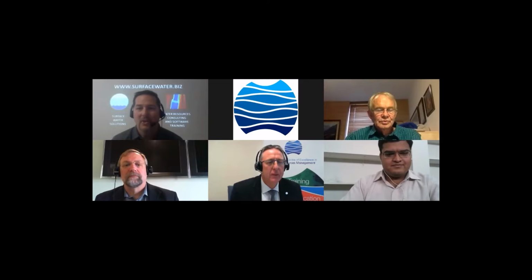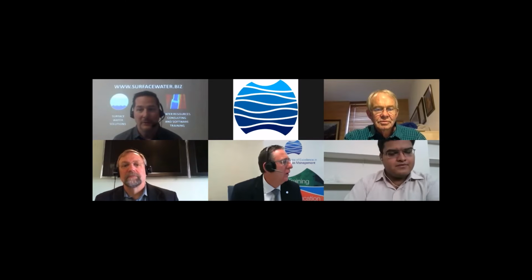If you're not able to come to the class, there's a blog called the HEC-RAS blog. Just Google the HEC-RAS blog and it'll walk you through a concept called terrain lifting. And that will show you exactly how to do it. And you just have to define it yourself. You define it manually. And then once you've defined it manually in 1D, then you can run that cross section any shape you like and pull the water out of it and lower your terrain to it. But probably much easier done in some civil design software than in HEC-RAS, but it can be done.